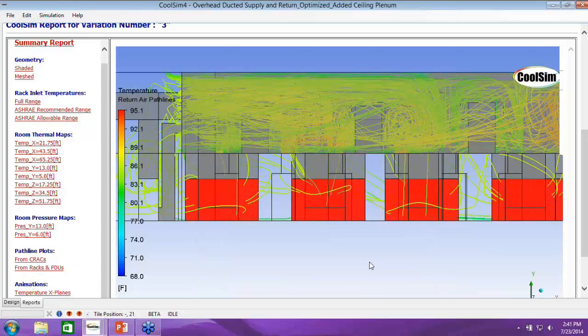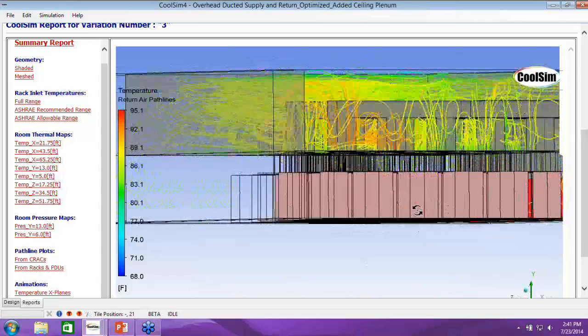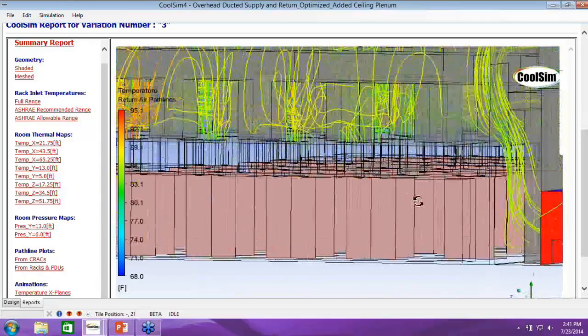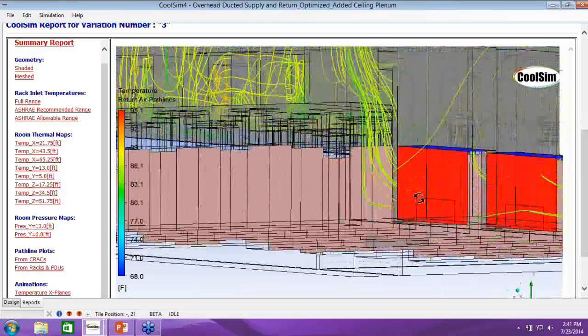It's a mixing issue, right, Magnus? No, exactly. That's what we said before, that the goal with air management is to avoid mixing. And by installing this drop ceiling, you actually did that. It's an enclosure technology. You separated the cool air completely from the return hot air.